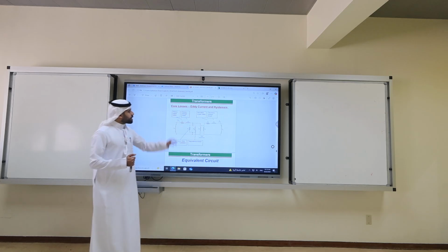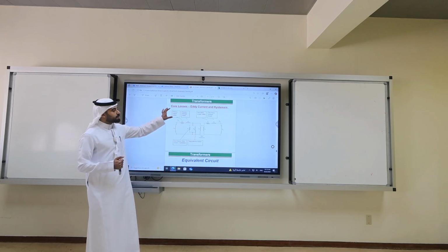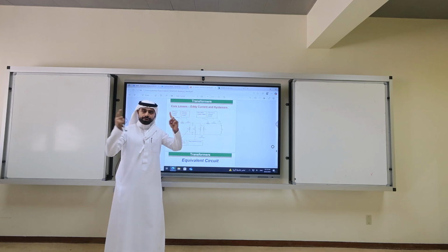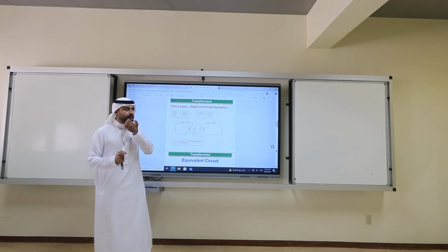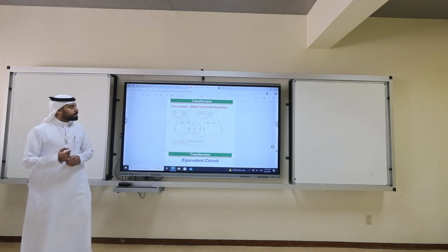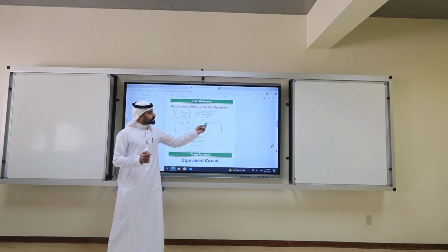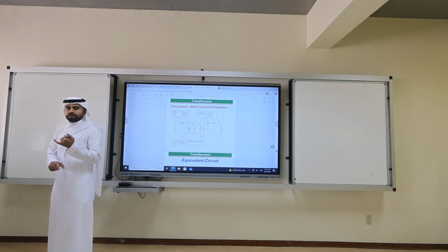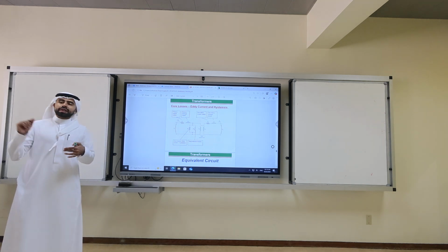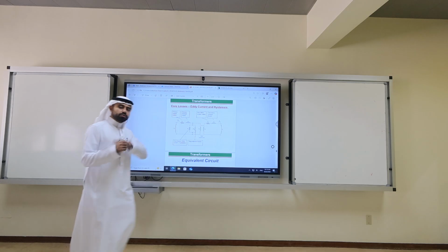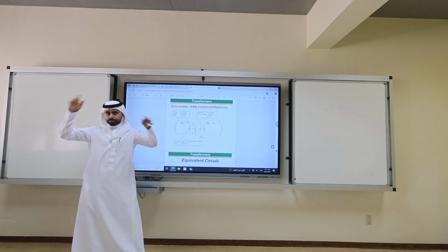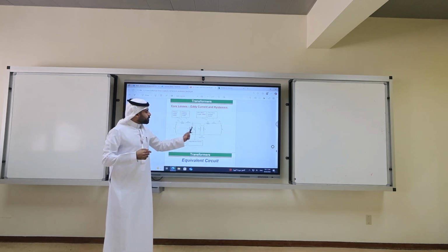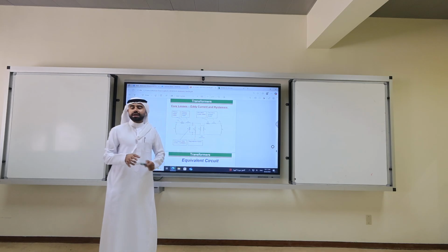RP is primary copper losses. RS is secondary copper losses. They are coils made of copper, and they have losses that appear also as heat. We have jXP, jXS to represent the leakage. What is a leakage? Fringing, if you have an air gap. The flux leaks between the coils, in the air. So how many components? 1, 2, 3, 4, 5, 6 on top of the ideal transformer.